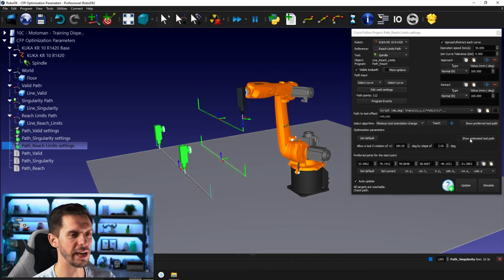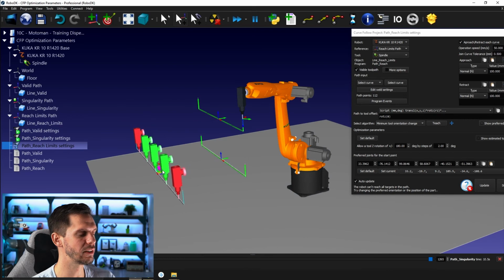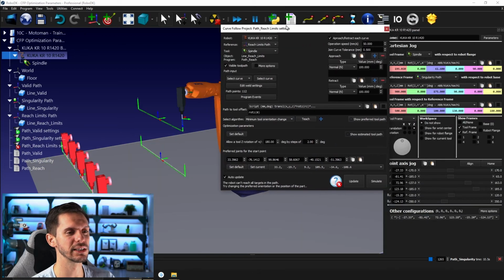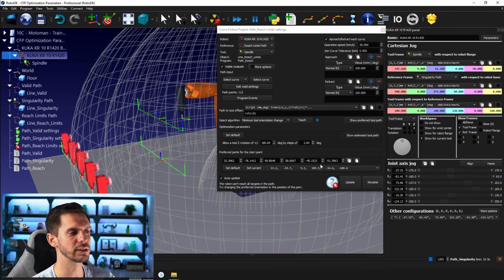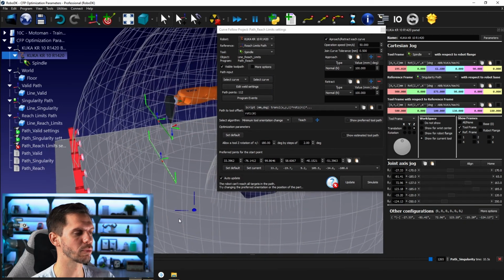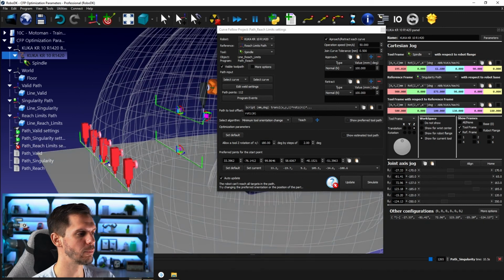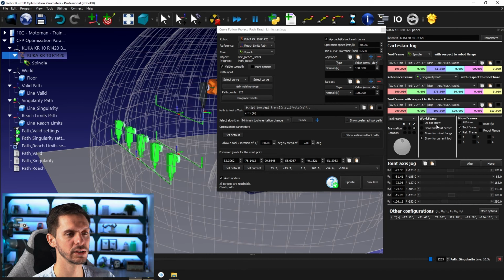So if I add a few more tools, let's say like that, I press Alt to move that frame here, and I move it further, you will see that at some point, some tools become red. So when the tools are red, it means that this point isn't reachable anymore. You're out of reach. If I double click the robot and just activate the show current workspace, you can see that you're already at the limit of the workspace. So it's possible that you can't reach those points. If I bring it back forward, here I can reach. Perfect. That's awesome. Don't need to show that anymore.